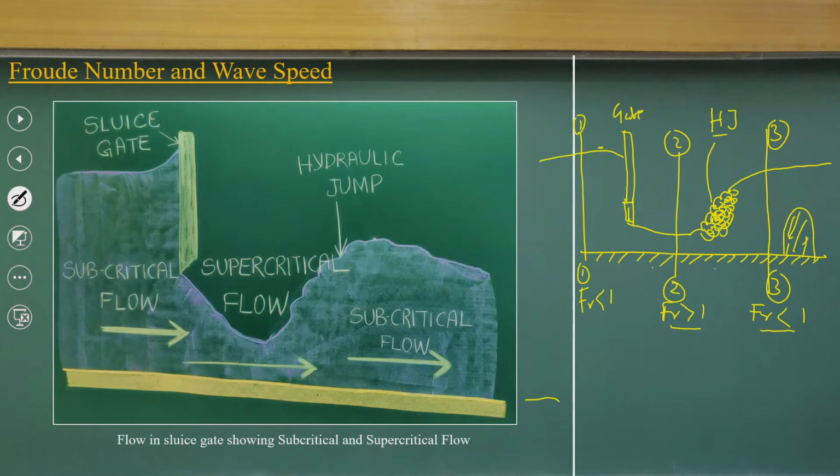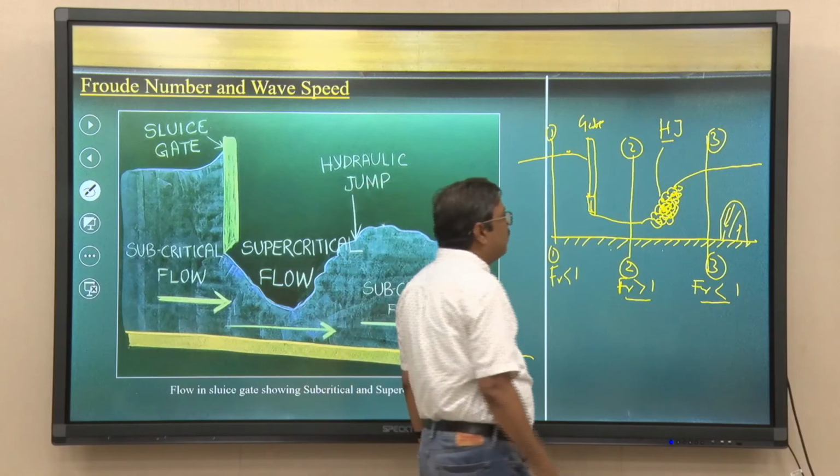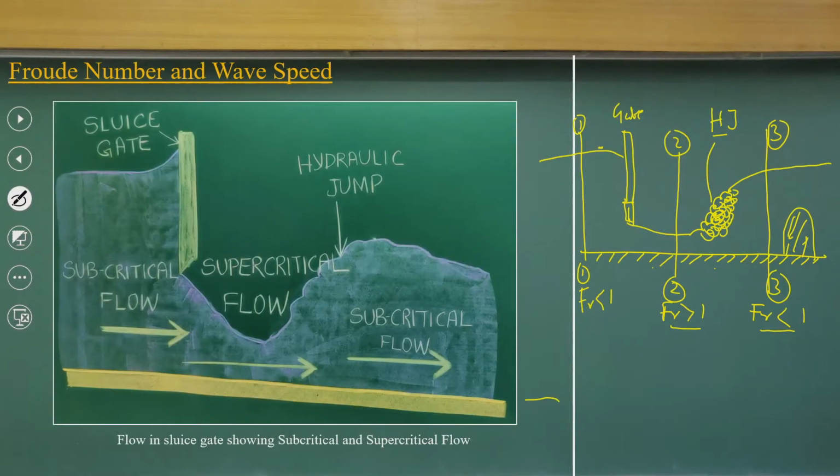We look at the hydraulic jump because it is a zone where we can have a lot of air mixing or chemical mixing. So in engineering, we also need to design in such a way that there is a hydraulic jump, which will create good mixing of any chemicals or air bubbles.